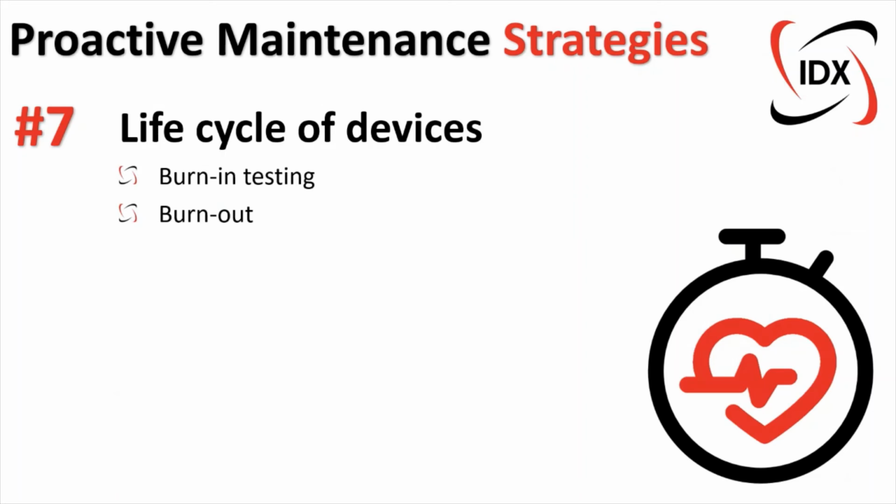Burn-in testing is where a company takes a proactive approach. So a manufacturer of PROFIBUS components connects the manufactured device to a network, runs millions of telegrams through the device, checks all the electrical behavior of the device, and ensures that the device performs according to its specification and build prior to putting a QA sticker onto the device and sending it off to site. This is extremely useful, and it's often very useful to ask the vendors and manufacturers that you deal with whether they conduct burn-in testing on their components, so that your site during your operations does not perform that function and identify faulty devices out of the box.